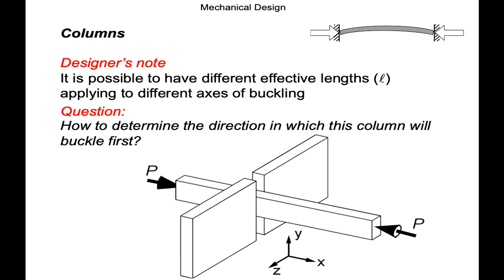At the end, there's no more information about how those free ends of the main beam are being supported. Let's just imagine it's a pin joint for now. And we could expect something like this. With what I did there with a pin joint, we expect that central zone to not move anywhere. So we've essentially limited the amount of lateral deflection, Euler style, that the beam can travel in that direction.